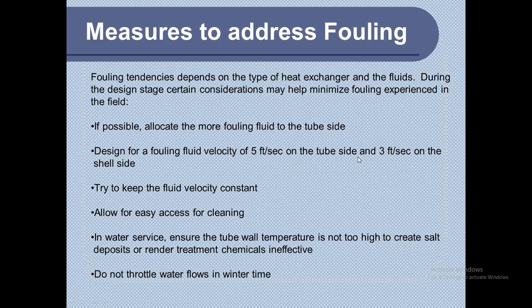So if periodic maintenance of the heat exchanger is followed, then this fouling could also be addressed, because regular maintenance and regular cleaning will not encourage this particular material to grow on the side of our heat exchanger.